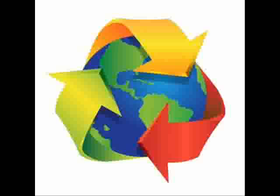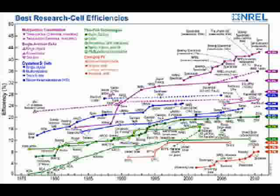The energy conversion efficiency of a solar cell is calculated by dividing the electrical power a solar cell produces by the sunlight power it receives. The efficiency of solar cells can range from 6% if silicon is amorphous to 40.7% if multiple junctions are used in research laboratories. However, the practical solar cells currently in the market are about 14 to 19% efficient.